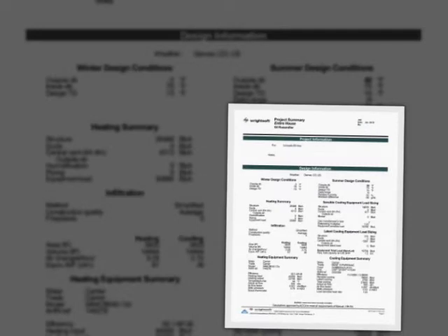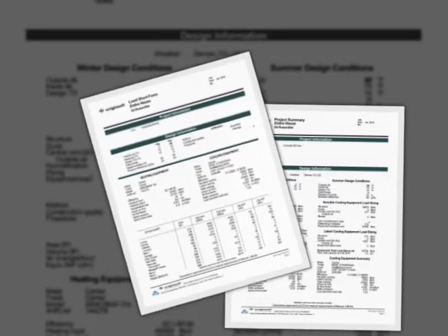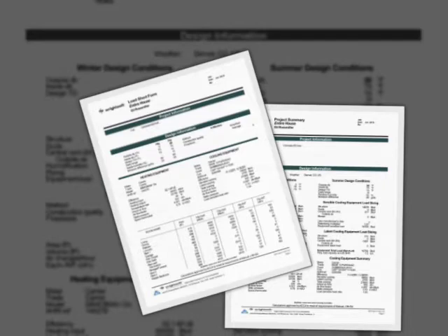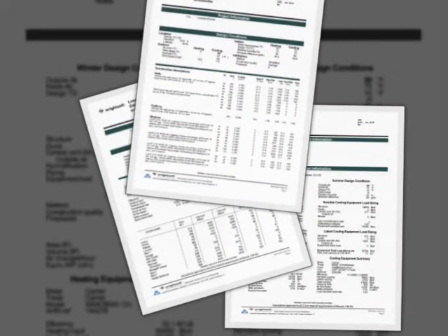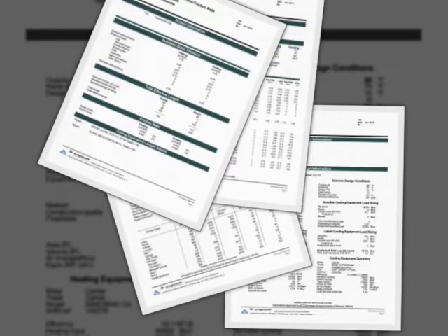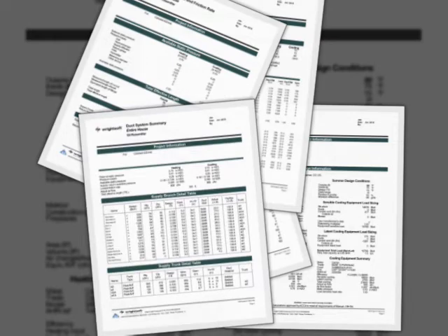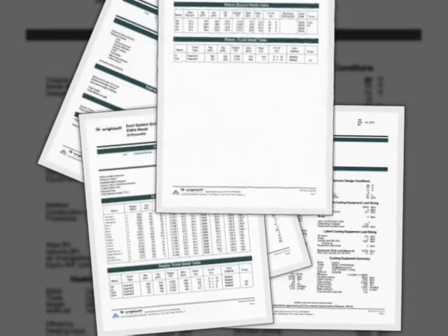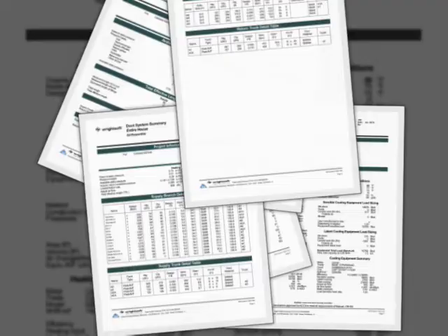I know that many folks look at a Manual J and all they see is a mass of numbers and have no idea how to make heads or tails out of it. Do not give up. We're going to do well on this critical calculation. Let me give you some basics and help translate those massive numbers into a recognizable heat gain and heat loss calculation. There are actually several ACCA approved software programs out there. Two of the most common that we see are called RightSoft and Elite.